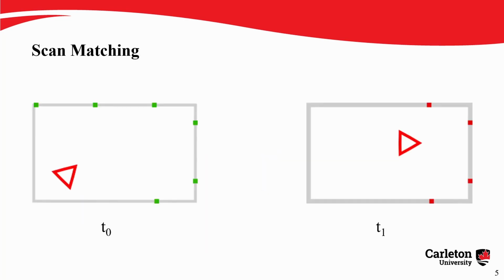One of the key aspects of SLAM is scan matching. When a 2D platform like a Roomba or other autonomous vehicle perceives its environment using a LiDAR, they generate scans like the ones shown here. A scan is simply a collection of points that represent the distance from the platform to the wall, which we've represented in gray. On their own, each scan provides an incomplete view of its surroundings, but by matching them together, you can simultaneously build a better map of your surroundings, as well as determine how your robot has moved from scan to scan.